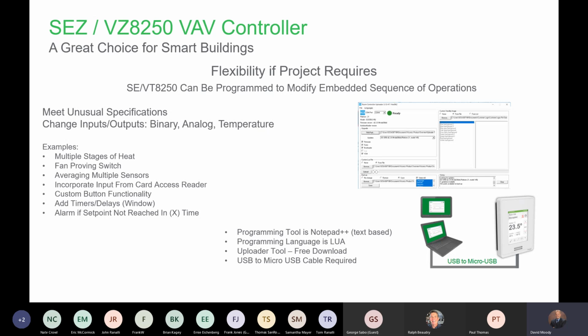And as I started this presentation, I was talking about a few years ago, I just kind of sat down and said, hey, I'm going to create this VAV program. I actually took an 8600 room controller, which is an RTU controller, and I wrote a VAV, basically what I've been showing you here. I wrote all of that in Lua to work in an 8600.